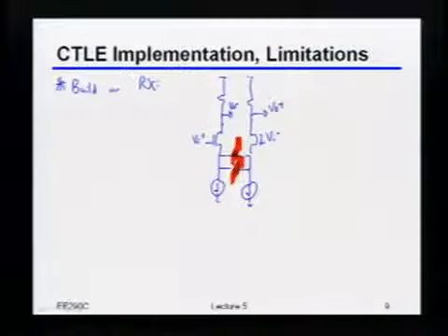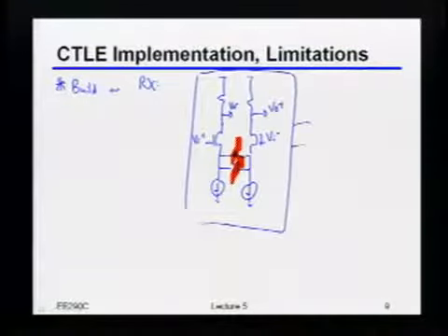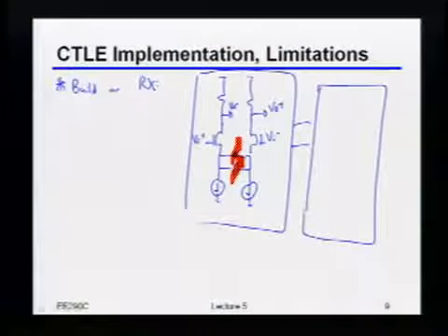How do you get more than 20 dB per decade slope out of the equalizer? Add one more zero. Okay, you said you could add another one, right? So indeed, you could, and just because I'm lazy, I'm not going to redraw the whole thing. I'll put a box around this. Indeed, you could take that and build another one like this. That's certainly true. Is that okay, or can we keep doing this?